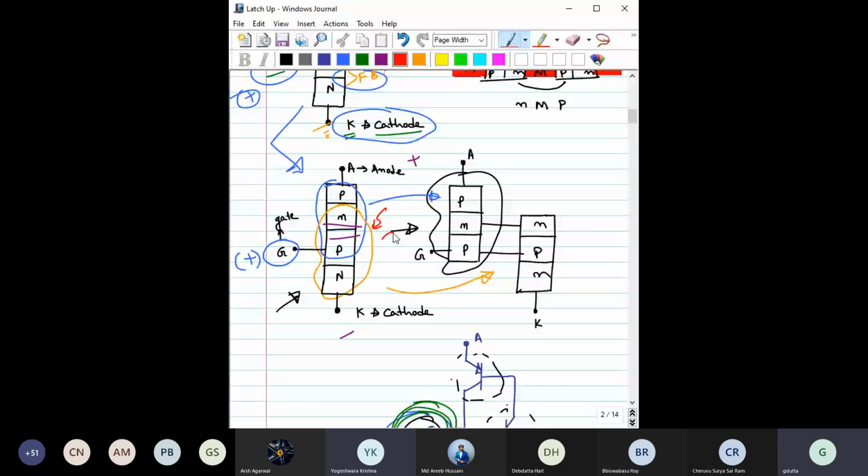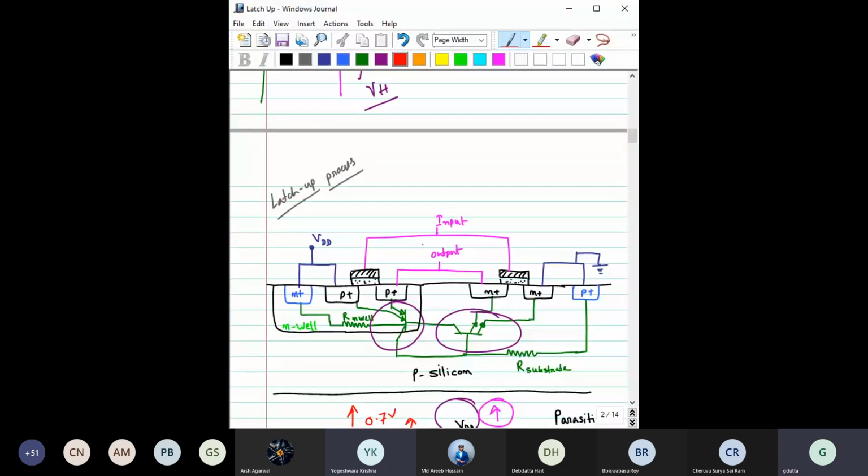Do you know what is the effect of radiation on a semiconductor? It will create a lot of excess carriers, meaning electron-hole pairs would be generated simultaneously, right? And that might create an avalanche operation similar to the avalanche operation here. So again, momentarily, all of a sudden, due to creation of a lot of additional charges, you could have latch up operation, right? So these are the primary three reasons for this latch up.